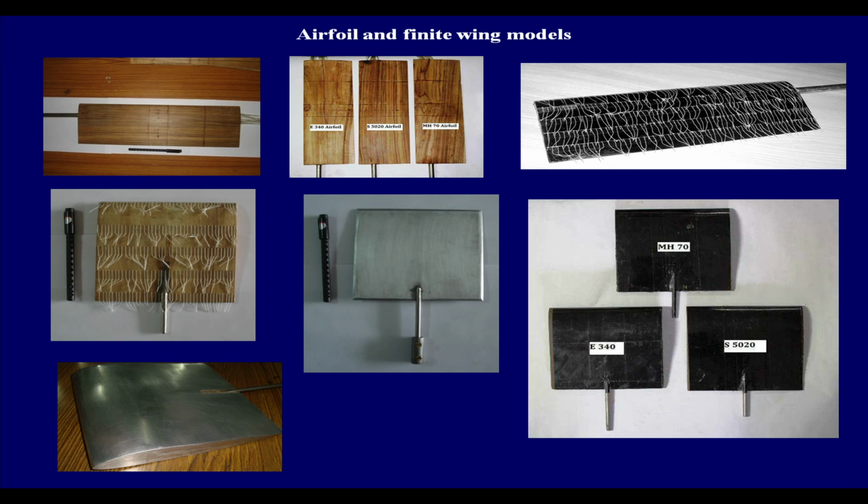So, there you will mostly see 2 things. A lot of work is reported on the NACA airfoils, different series of NACA airfoils. Moreover, they talk about things like Reynolds number dependence on, say, lift curve characteristics or drag polar and things like that. So, they are concerned about how Reynolds number may be having an effect. Moreover, they generally talk about Reynolds numbers in the range of millions, and those ranges are actually more relevant for traditional aerospace applications, the full scale aircraft and things like that.